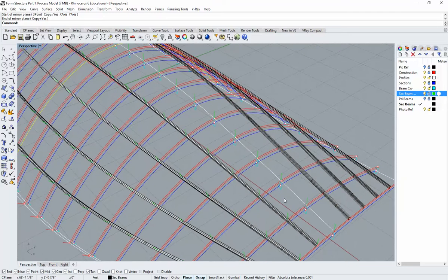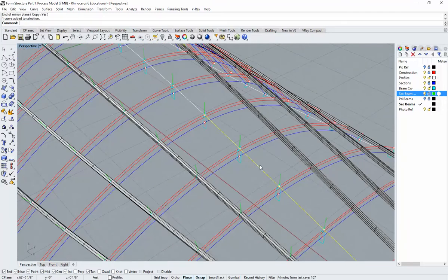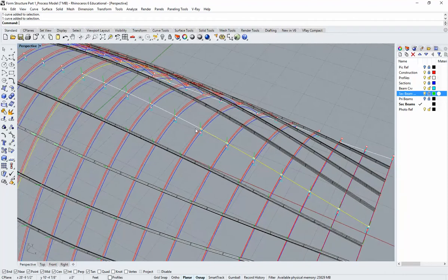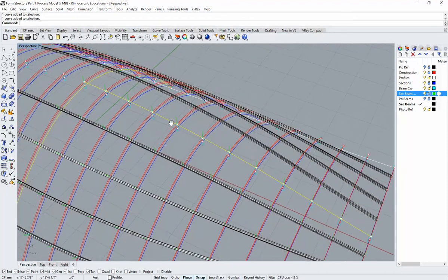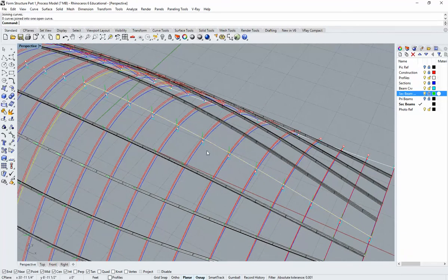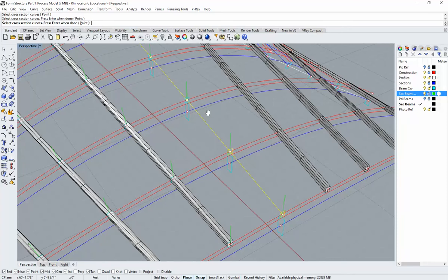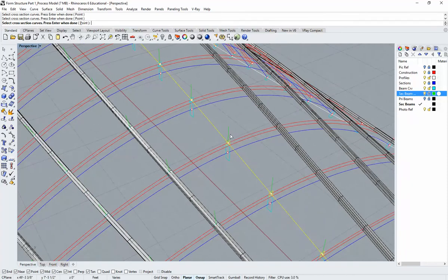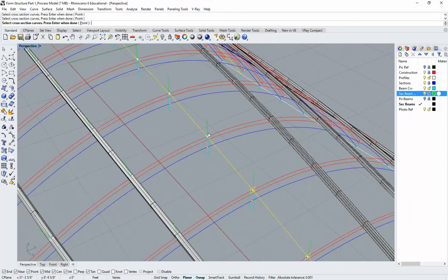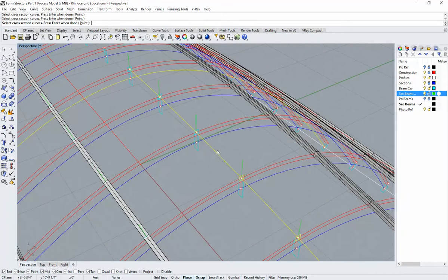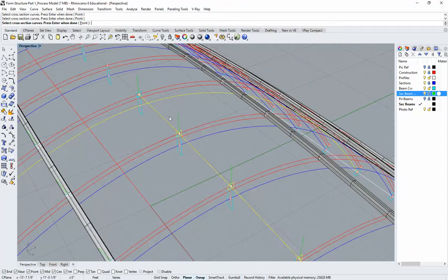And this one, again, I don't have to break this into separate segments because there's no rotation between the sections. So long as these are all separate. Yeah. You know what, so I'm gonna join those back. Looks like I exploded it by accident before. And that's fine. So now what I can do is just run the sweep command. This is my rail. So it's one rail all the way through as a polyline. And I'm just going to select, just to be sure, all of these cross-section curves. To be 100% sure that they match, you know, where I want them to.